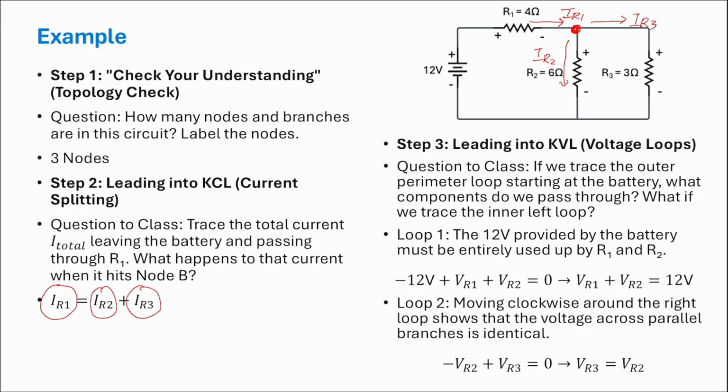Step 3, what is the KVL? Now we can track the KVL. The first thing is to choose the loop. Let's first choose this loop here, and we find the positive and negative across each component. They're already marked here. When the direction of the loop enters the 12 volt, it enters from the negative side, so this is negative 12 volt.